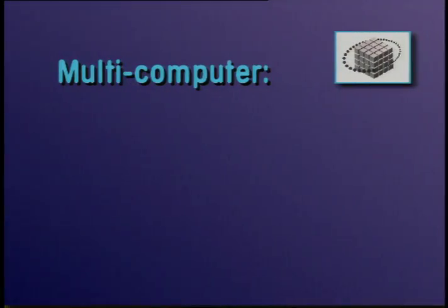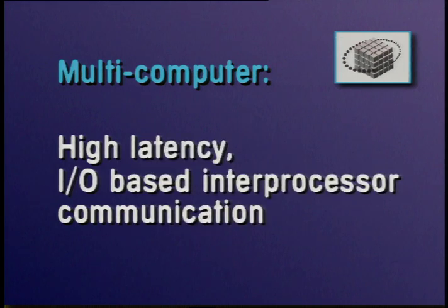Many MPP systems to date have been designed as multi-computers, not multiprocessors. Interprocessor communication must depend upon explicit I/O-based requests. Data moving from one processor to another must pass through the I/O ports of the processors. This usually requires the use of processor interrupt mechanisms and even intervention by the operating system. The target processor must decode or interpret via software techniques the address tag and the purpose of the message to determine the exact source or destination for the payload. This results in significant increases in latency for the interprocessor communication process.